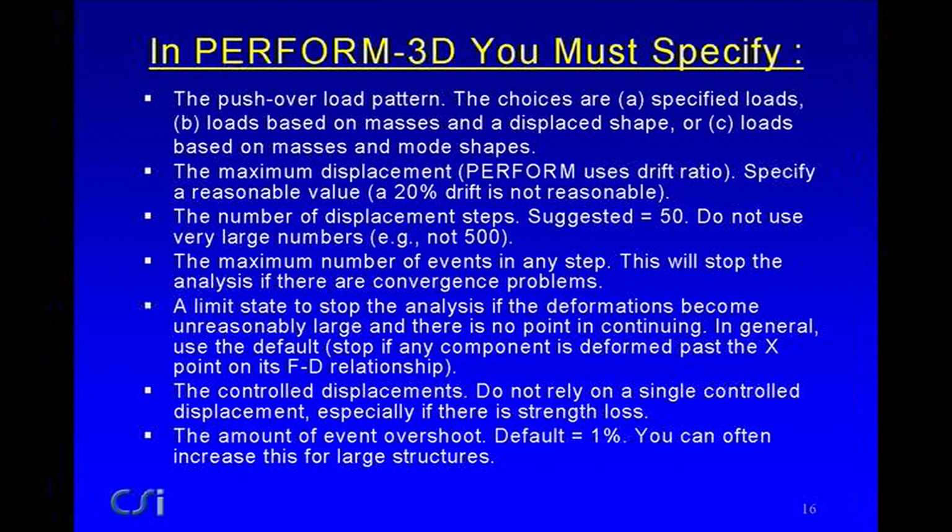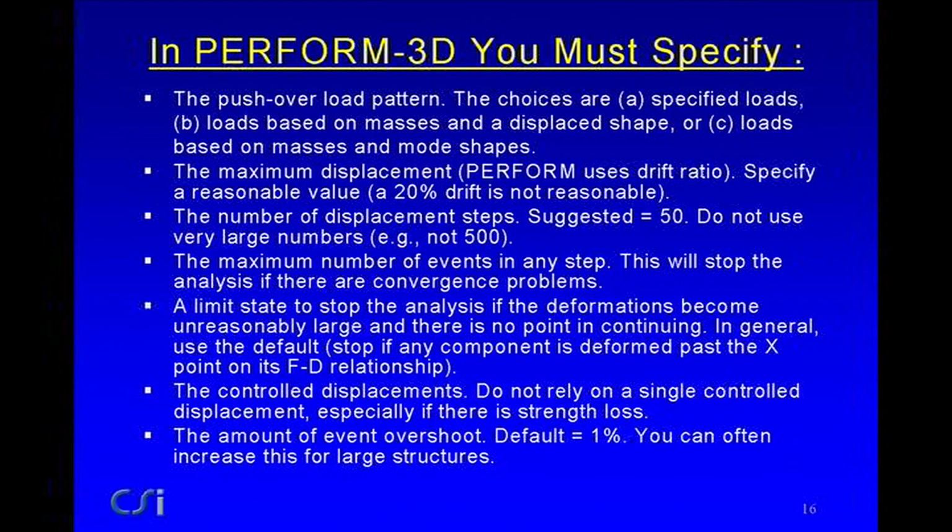Thirdly, the number of equal displacement steps that you want. And I suggest maybe 50 as being a pretty good number. I do see people using 500, but that's really overkill. In fact, it creates problems because if you have a very large number of very small steps, the displacement control method can get a little unhappy because you get so little load increment it can get messed up. It's better to specify 50 or maybe 100 steps, but no more. You don't need to do any more than that.